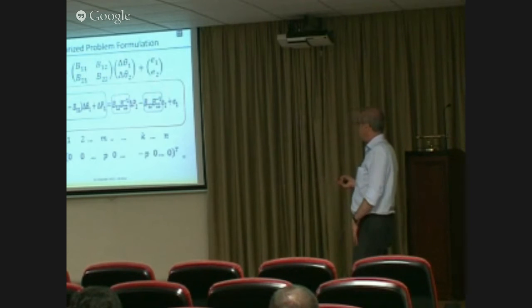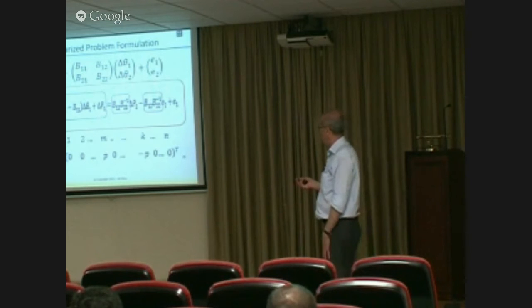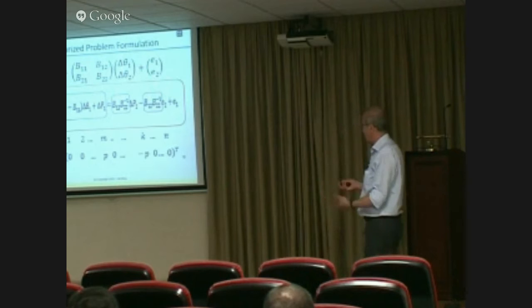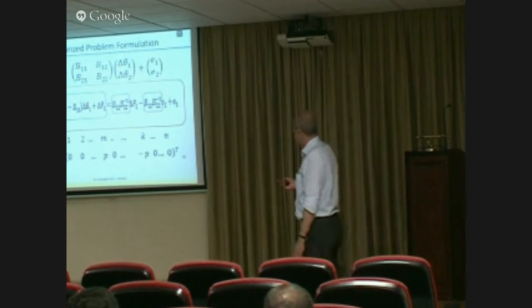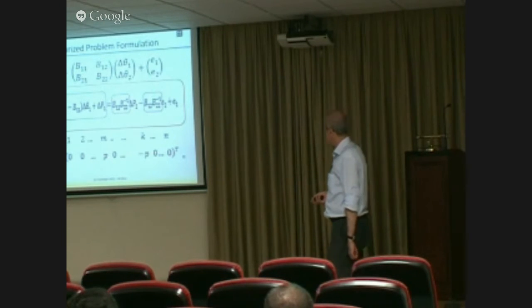And this equation, the left-hand side here, can be known, because these relate to the internal system variables, the state and the injections. And then the external system, of course, we don't know. So delta P2 is the unknown. But we know that this unknown, in case of this line outage, will look like this, all zeros except for these two entries.